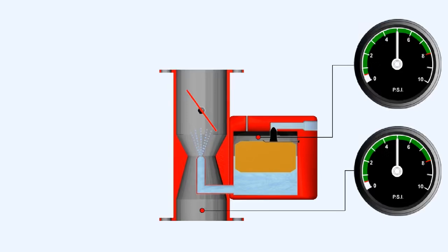The U-tube principle, one of the two principles upon which the operation of the carburetor is based, requires that the pressure in the air intake and the float chamber be equal. Admitting atmospheric pressure in the float chamber by means of a drilling in the float chamber cover plate is not a satisfactory method of ensuring equalized pressure across the carburetor,